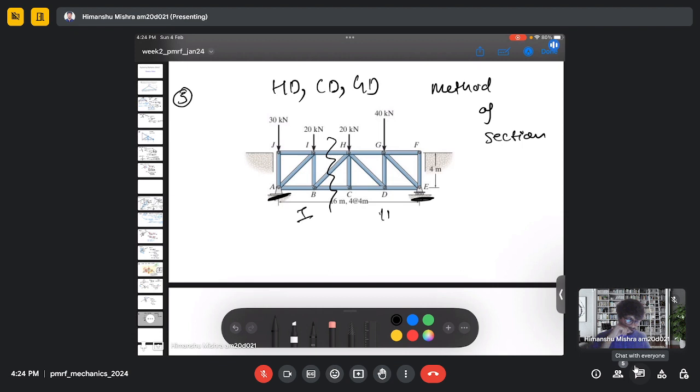This is my first part and this is my second part, and then we do the moment balance analysis in either of these parts. So in order to do the moment balance analysis, first always calculate all the forces which are there. For example, calculate the normal reaction force at A and divide the truss in such a way that it cuts at most three members. So here we cut this member, this member and this member. Now, by using the method of section, we can calculate the forces in these members.